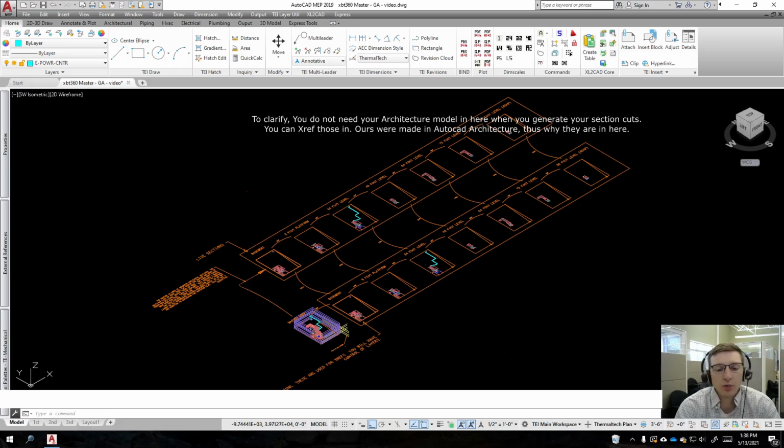Last time in the Global Cut Planes video, we outlined some of the pros and cons of using the Global Cut Plane, when it applies, and what objects it affects. Now, if you recall, Global Cut Planes only affect AEC objects. That's architectural, engineering, and construction objects. AutoCAD has what are called tool sets that insert and create these AEC objects. An example of this would be pipe, duct, conduit, cable tray, multi-view parts. Those are all going to be AEC objects.